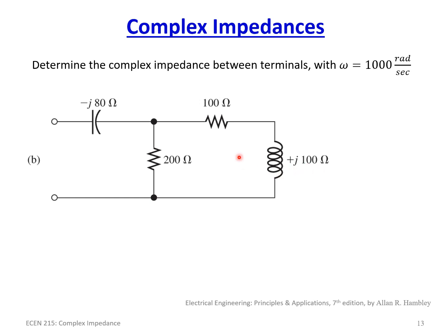So not to get confused with this, we can also convert these little boxes. But first, now that we know this, we can actually convert this first part into an equivalent impedance. So we have a 200 ohms in parallel with a 100 ohm resistor in series with j100. So we can automatically say we know what the impedance of this is because it's series. With series we add, so we end up with 100 plus j100. And then we're going to have that in parallel combination with the 200 ohms.